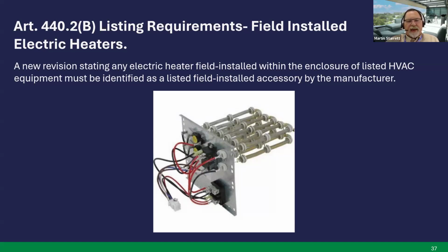The new revision states any electric heater field installed within the enclosure of listed HVAC equipment must be identified as a listed field installed accessory by the manufacturer. You're not going to be able to take another brand or whatever and install it in the equipment unless the manufacturer of that equipment says you can. So you're really going to have to pay attention to when these are field installed. Next slide.